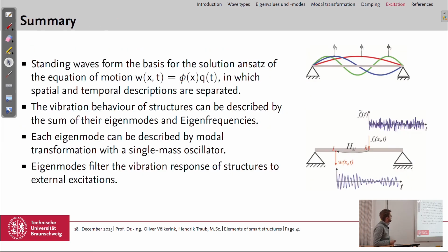So, with this, we are already coming to an end of this introduction to vibration and modal analysis. Standing waves form the basis for our solution ansatz of the equation of motion, because then we can separate the description of the vibration shape in the eigenmodes and the variation in time, the modal coordinate. We can describe the overall vibration behavior of the structure with the sum of their eigenmodes and eigenfrequencies, or with the sum of these single degree of freedom oscillators.